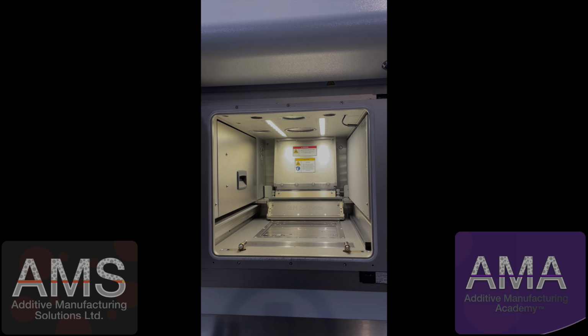The recoater is shown at the back, which is a dosing unit with the words SLM Solutions written along the front. With the build plate in the machine and the build plate height set based on the thickness of the layers we want to produce. So for example, that could be 30, 40, potentially 60 microns. So likely around half the width of a human hair.